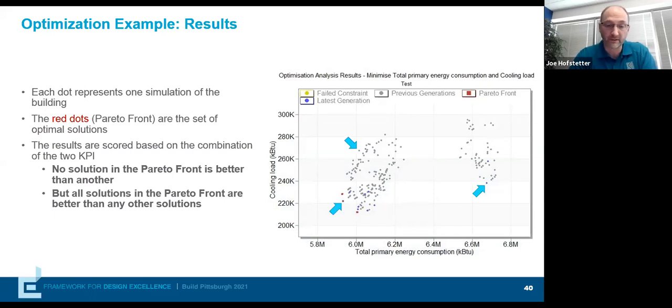A real world example of this could be the shading coefficient of your glass or the exterior shades on your building, where they're helping reduce your peak load in the summer. But what you might actually be hurting yourself with is the reheat load that you're dealing with in the winter. The free solar heat that we gain in the winter for our climates might outweigh the cooling benefit that we get in the summer.